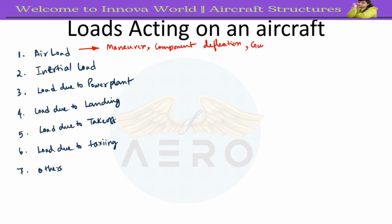Then gust, that is heavy wind, turbulence. Then component interaction. If there is a combination of wing and fuselage, there will be some aerodynamic interaction between those components. If it is a biplane, or the wing and the tail are closely connected, there will be different kinds of air loads. All those things are connected with air load.